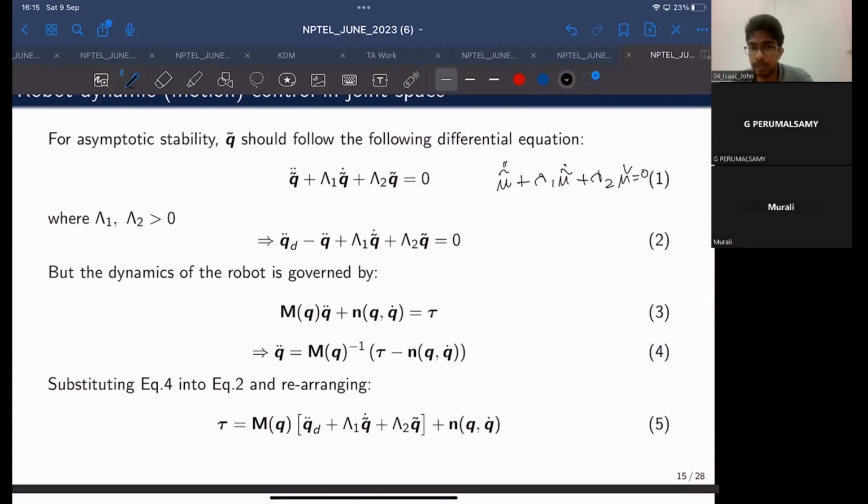Right, and there are a lot of manipulations that you have to use, because this mostly deals with the transformation of matrices, or transformation of parameters like M and this vector N from task space to joint space. You know what this mu double dot would look like, right? The equation of motion in task space will look like F is M of mu, mu double dot plus N of mu, mu dot. This is going to be F. All these sorts of things.